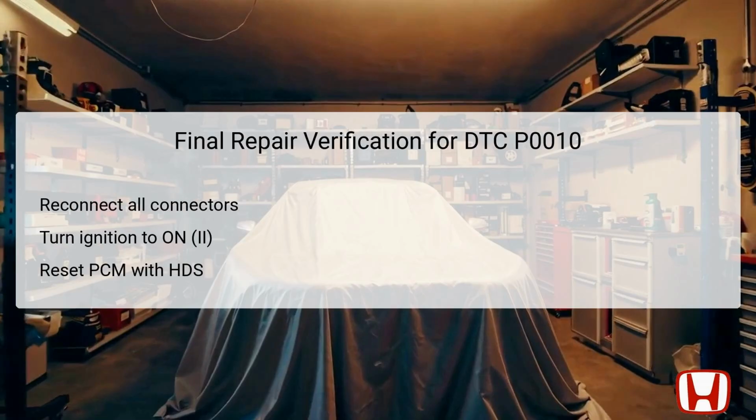After completing the troubleshooting and any required repairs for DTC P0010, it's essential to perform a comprehensive repair verification to ensure the issue is fully resolved. First, reconnect all electrical connectors previously disconnected during the diagnostic process, ensuring secure and proper connections to avoid further issues. Turn the ignition switch to the on position to power the vehicle systems.